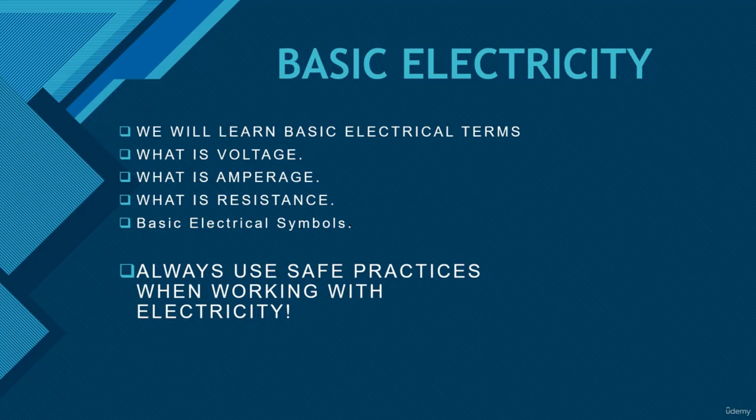And, as always, please use caution when working with electricity. If you're replacing a part, disconnect the electricity, use your meter to verify there is no electricity present, and then you can proceed with replacing the parts. Now, you will have to do some diagnosing with live electricity, so be careful. We're going to cover that stuff as well.